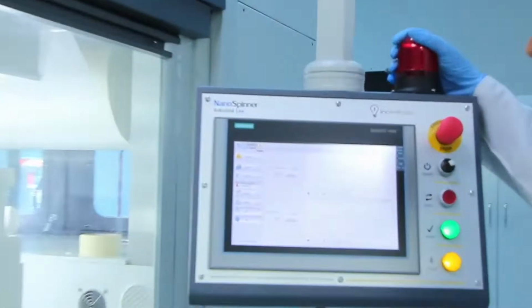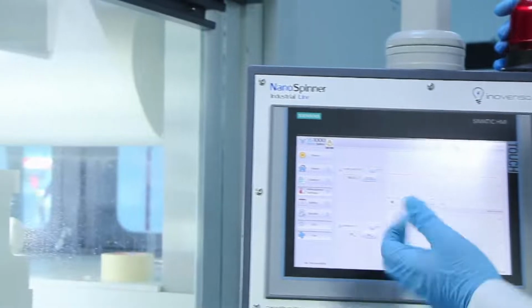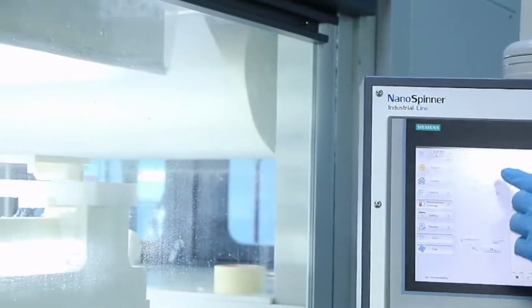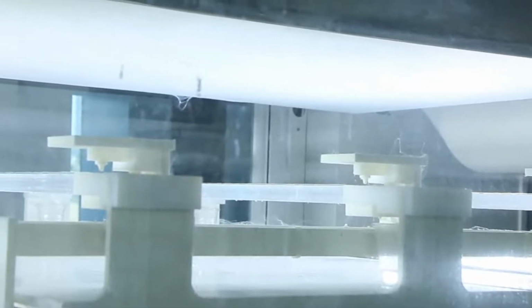Right now the spinning is perfect, but if you need to adjust or tune the ambience inside, you can do so by turning on the heater. Can go up to 40. So our target is 40 degrees Celsius, and humidity is 34. Now we've activated the dehumidifier and the temperature, and they're going to increase the temperature to 40 where we set it, and reduce the humidity to 30 where we set it.